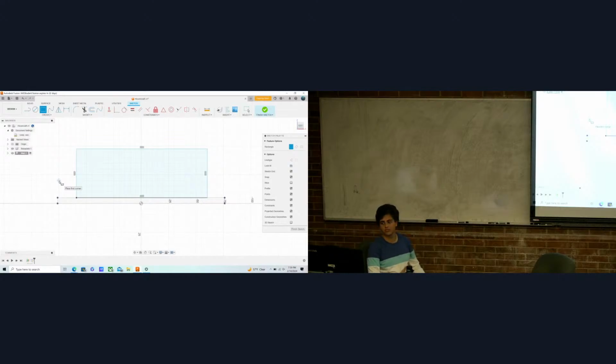Okay. Now you just want to draw a rectangle, snap into this. You just make a 2-point rectangle. I would just put it in the middle. And then just make sure it's not construction line type. Before you go, you want this to actually show your sketch. You'll just unclick construction. And then you want it snapped onto the base, so the top line right there. And we'll explain why in a bit.